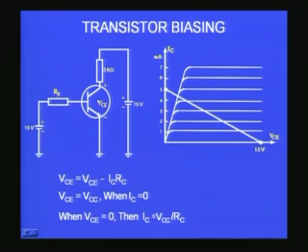The answer is indeed yes, you can do that, because you have the voltage and the RB. With this you can forward bias this base emitter junction and you can maintain a constant current. If necessary, you can vary these or choose a proper value of RB and VBB and you can maintain a constant current. And with the 15 volts here and the 3K, because there is forward biasing, there will be a current in the collector and the emitter, and therefore that will correspond to a voltage being developed across the collector and the emitter regions of the transistor. So, it is in principle possible to bias in the simplest way by using two power supplies and two resistors.